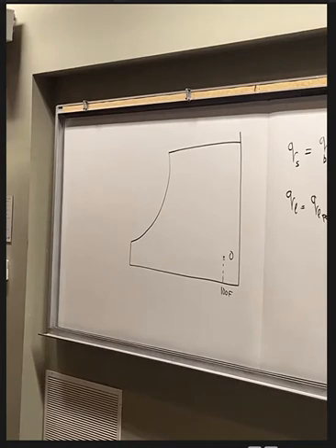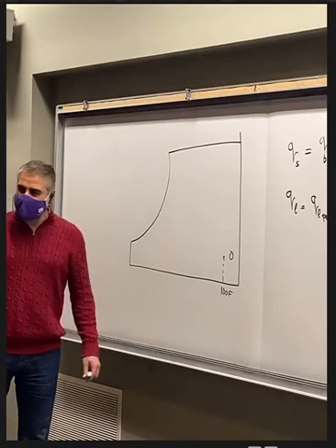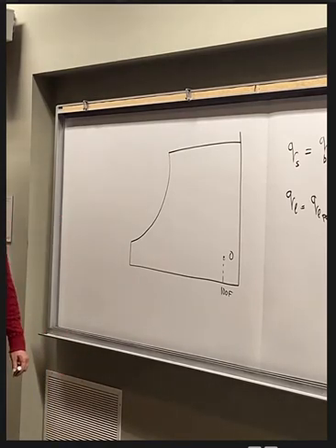So the air, it's 100% fresh air, so there is no return air. The air goes through filter and it goes through air washer. The air washer is an adiabatic humidifier that uses water for humidification. So that means the air will leave at higher humidity and lower temperature. And in this case, the air washer was able to reduce the temperature by 20 degrees.